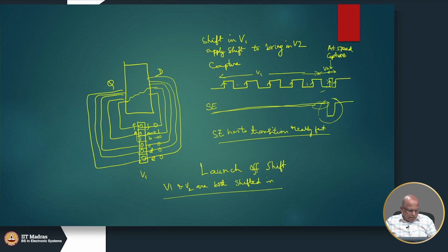So transition delay faults are required because there may be circuits which have a speed issue, possibly because vias are not properly formed, right? They have a high resistance, or whatever could be the reasons. So we apply the transition delay fault model and generate test vectors. We may follow either launch of capture or launch of shift.